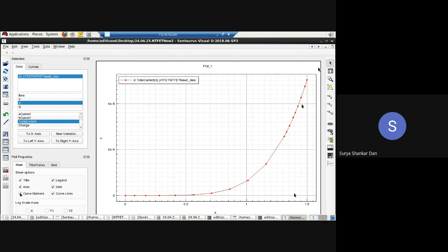If you increase the voltage, you are going to get a higher on current. But remember one thing, that really doesn't make any sense, because when you are actually deploying the circuit at some particular technology node, then the VDD will be fixed at 1 volt only. Right? So what will your on current be? On current is the current which is essentially obtained by the device when you have applied VDD to VGS. Okay, now which VDD will you fix?